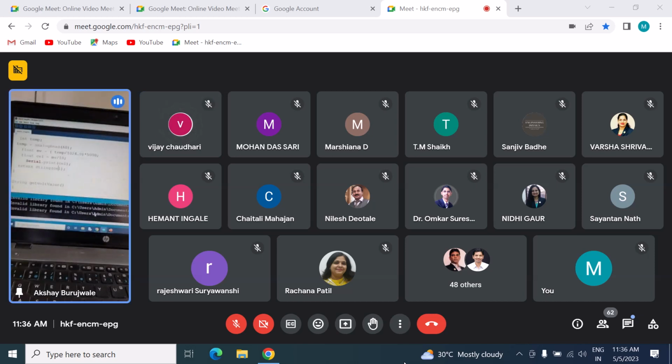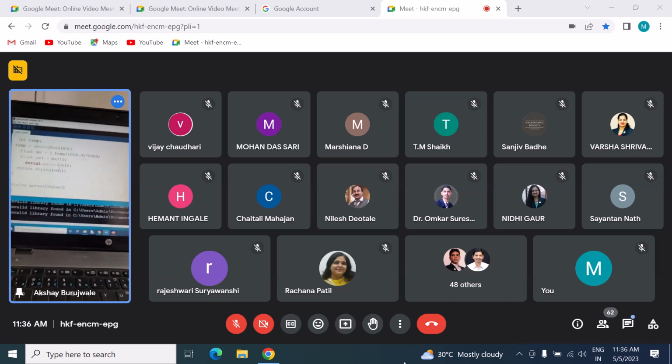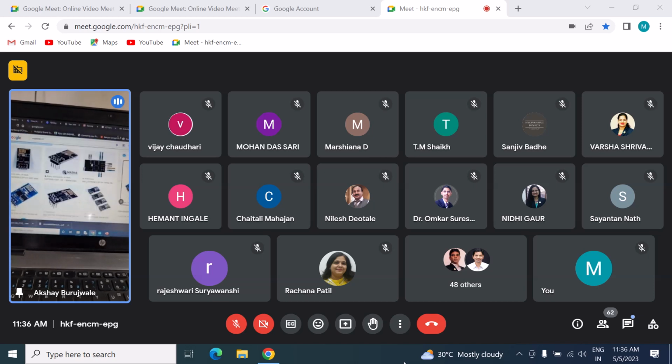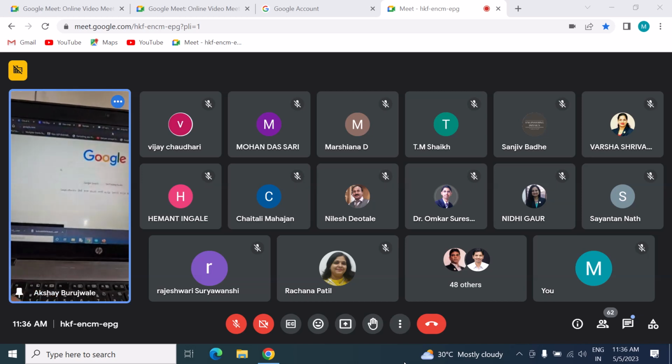So for that DHT11, we have one library called DHT. Okay, I can show it. Examples. So the DHT library sensors. It is available on GitHub. We can go for installation of this: in the Tools, then Sketch, then Include Library, Manage Libraries, and in the manager you will see the online DHT11. Okay, it will take time. You can open it side by side. Okay, this is the DHT11 sensor, a library for Arduino, on GitHub.